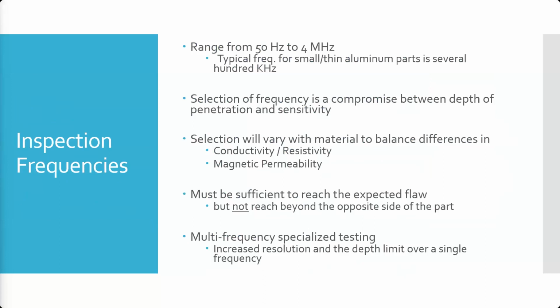And as I mentioned earlier, you can have multi-frequency specialized testing where you can get an increased resolution over various depths rather than a single frequency. It does a low frequency pulse, then a high frequency pulse, then a low frequency pulse, then a high frequency pulse. It looks at the surface, looks deeper in the part, looks at the surface, looks at the backside. And it's doing that very, very quickly, fast enough that you can take your probe and move it around on your part, and you're not going to know when it's doing top or bottom. It's doing it several times a second.